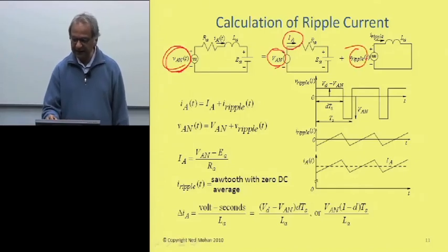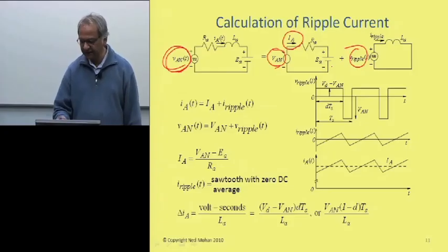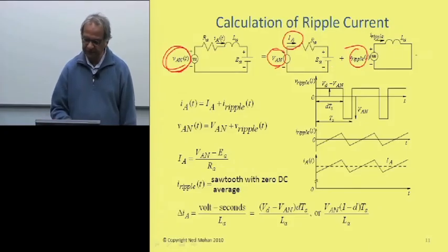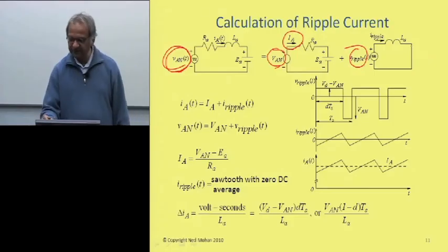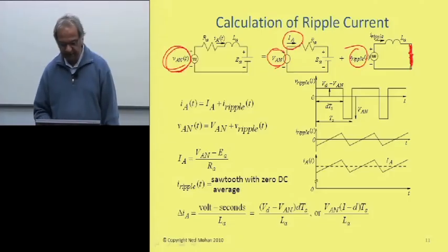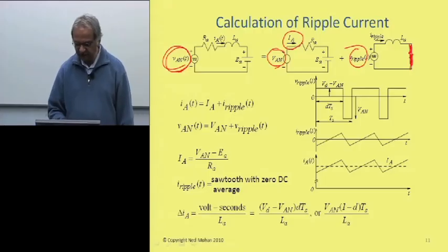And in that case, you can forget about the resistance, and of course the DC voltage, because we're using superposition, would disappear. You can of course include this resistance, but it's so small that it's negligible compared to the reactance of this inductor over here. So we can just neglect that. So that's what is shown over here, that we can calculate what the peak-to-peak ripple would be.